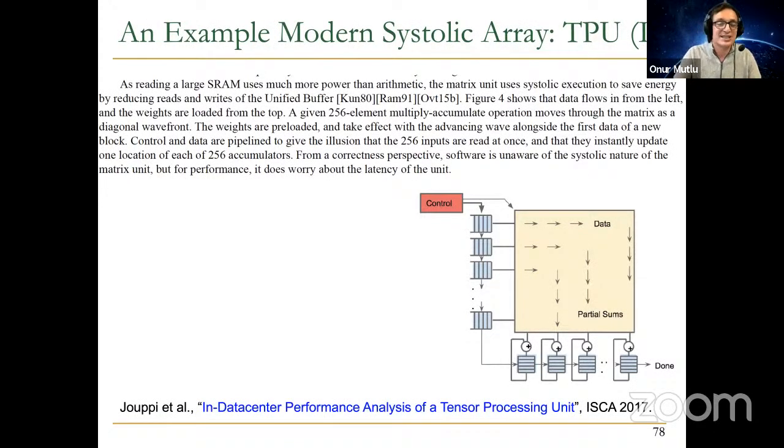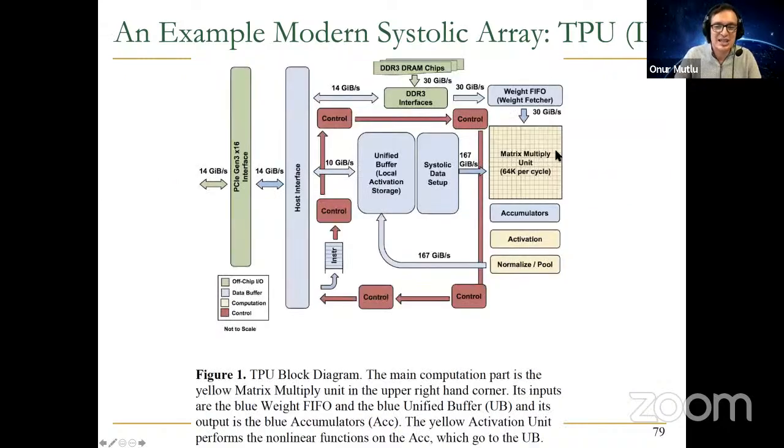Okay, so we've already discussed systolic arrays in digital design and computer architecture. We may actually talk about some papers related to systolic arrays in the seminar course also, but some of you may know how it works. I'm not going to talk about that in detail, but it's essentially a big matrix multiplication unit. You can see that there are 64,000 element matrix multiplications that happen per cycle. And on top of this, you can accumulate, so you can do floating point multiply and accumulate in this systolic array. And this is just the first generation. The next generation may be bigger.